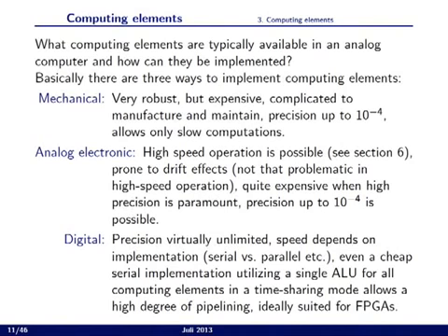Then you could use analog electronic implementations of typical computing elements. Analog electronics allows very high-speed operation. If you build integrators with capacitors in the range of a nanofarad or the like, you can achieve repetition rates for solving differential equations in the area of tens of kilohertz, which is next to impossible with a digital computer.